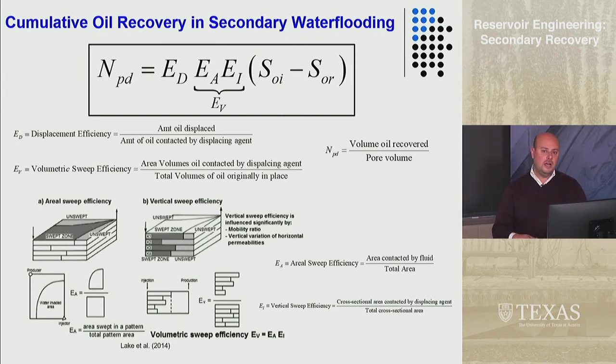So when a low viscosity fluid like water, or a high mobility fluid like water, where mobility is the relative permeability divided by the viscosity, displaces something like oil, which maybe has a higher viscosity or at least a lower relative permeability, then you'll get unfavorable displacement, and you'll get what's called viscous fingering. And basically, the water bypasses the oil and finds the producer well, which is no good. Those are all examples of unswept oil, and there are 3 different kinds.